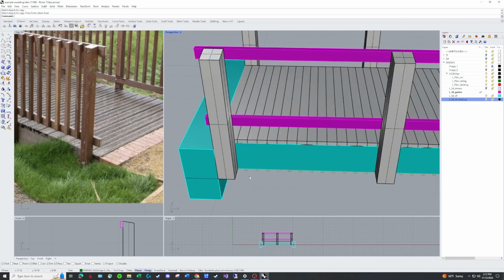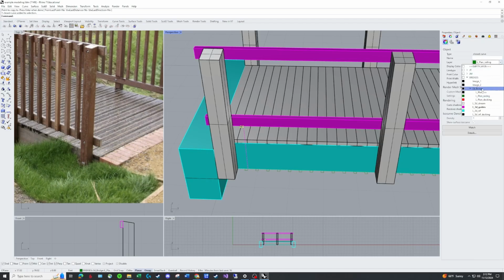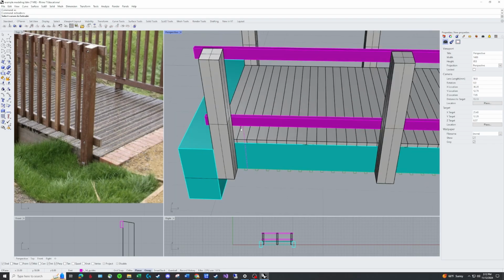I'm just going to copy, actually, polyline, and I'm going to go perpendicular here, copy this up. And because this is part of my plan view, I don't want any of that stuff in 3D. That way I can just turn off all my 3D line work. I still have my drafting. So extrude curve, this is kind of an extrusion fest, but when you have these architectural pieces, it tends to be that way. So choose a point to snap to, and we'll just snap this like crazy.